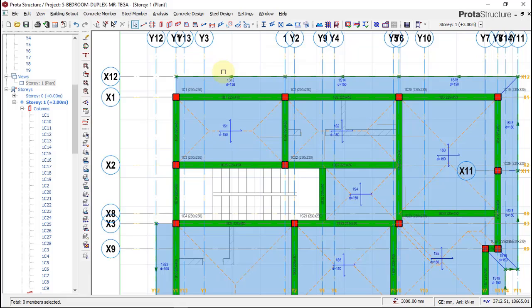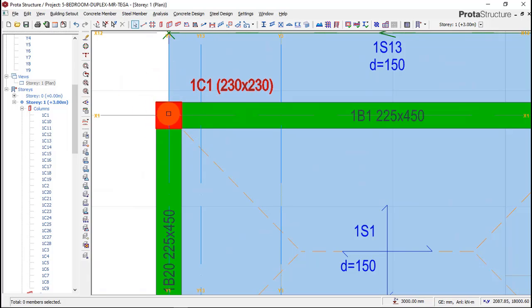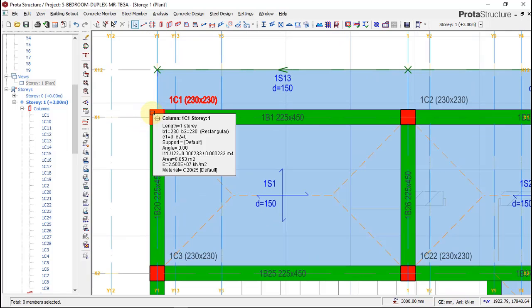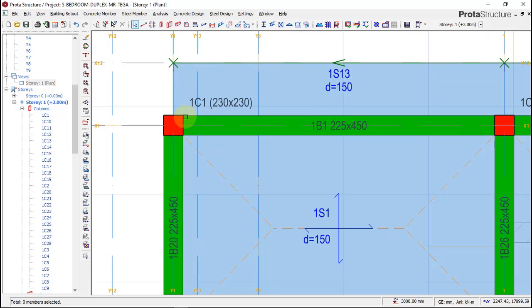Many people like to insert Storey once they are done with their modeling, but for me, I'm not done with my modeling until, just as when you're performing your structural design manually, we obey the fixed end, the pin end or the roller support and all that. So I always obey the fixed end and the pin end condition. At this area, I always hinge, because moment at an end must be 0.